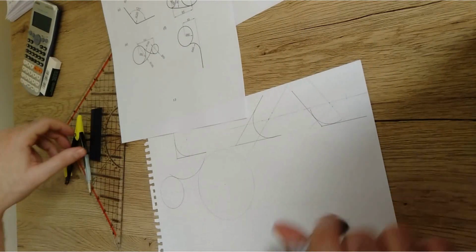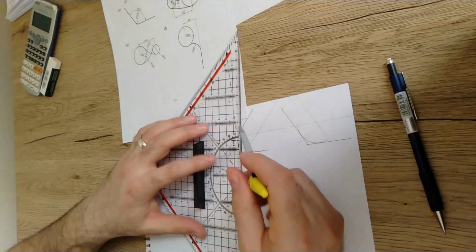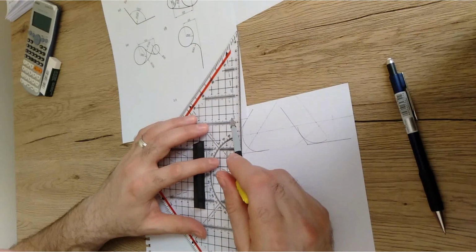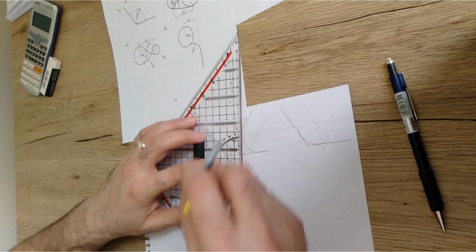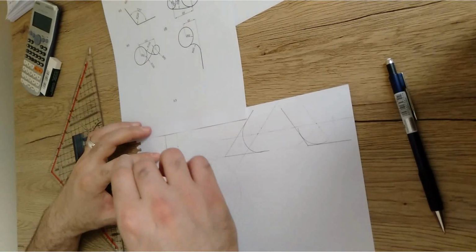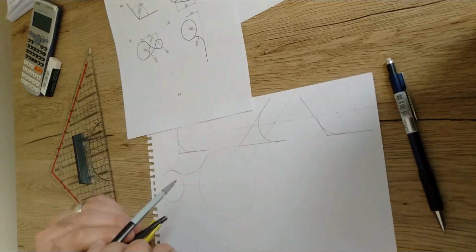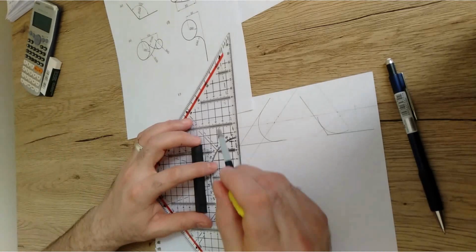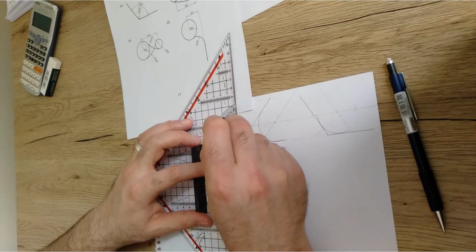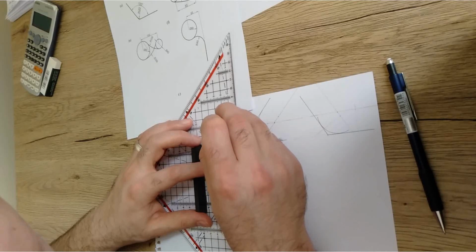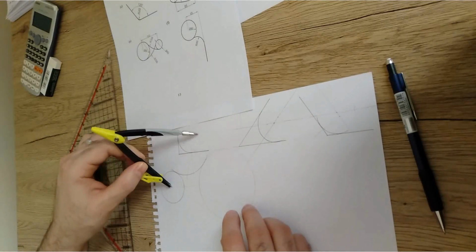So from this big circle, I'm gonna fix and open the canvas by the 100 negative 40, which should give us 60. Then from this center, I'm gonna draw a curve. This curve should be the locus of the first center point, or the first locus. Then from this small circle, I'm gonna open the canvas by the 80, which is 100 negative 20. So it should be a little bit bigger in this case, and this is gonna give us the second locus.